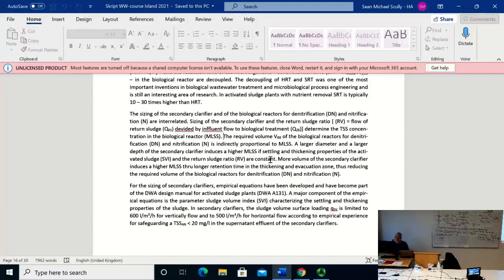This is only relevant when you already have an existing secondary clarifier and you want to calculate the capacity of that. Then you can say, if I overload it, and if I put on a higher hydraulic load, I'm conscious that I will not get my 5.3 grams of total solids in as MLSS. But if I have sufficient volume in my bioreactors, then I can say, okay, I can make a compromise. I just need maybe 3.6.